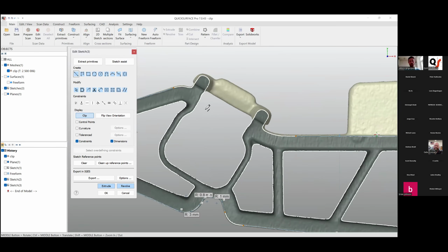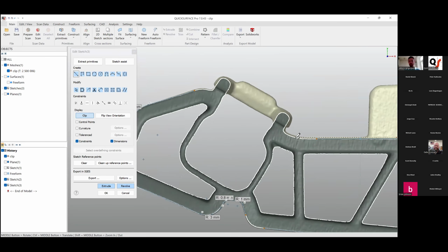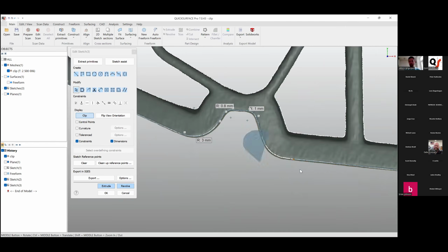And another cool thing, if we select here line, for example, you want to draw some line that would snap to splice points, you can hold Control button and it automatically snaps to these points. In many cases, it's useful. For example, it's here. So you cannot actually select some mesh points right here because you just don't have them, but you can snap your line to these points.